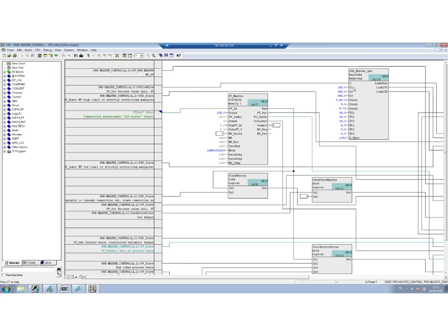In this block you can have, well, 3 operating points. So here 100 liters per minute, 500 liters per minute, and 900 liters per minute for the product flow. And here you have the associated controller gain, right? So in between there will be linear interpolation. As you can see here, TI is constant and TD is constant.